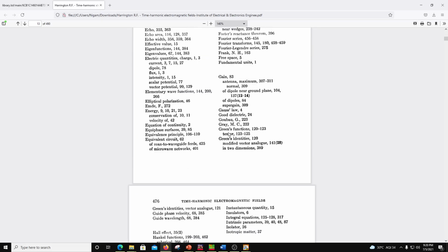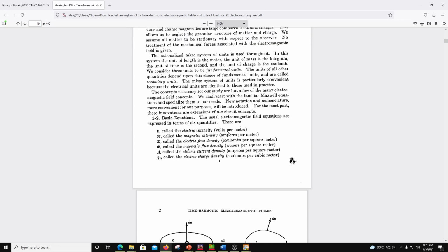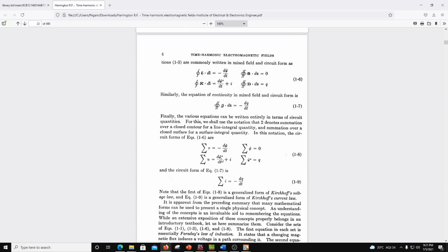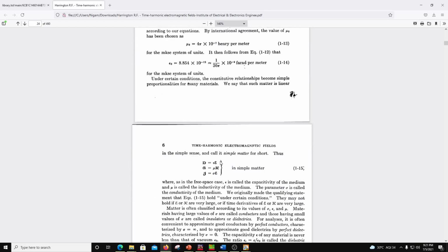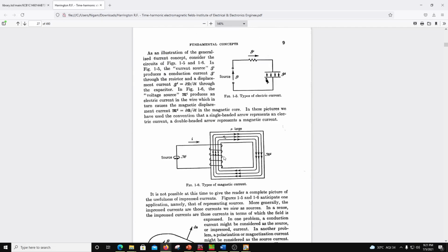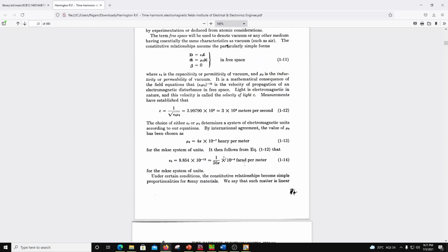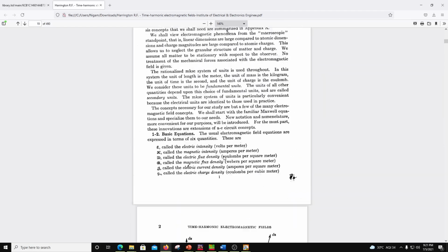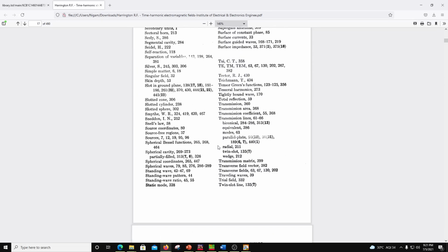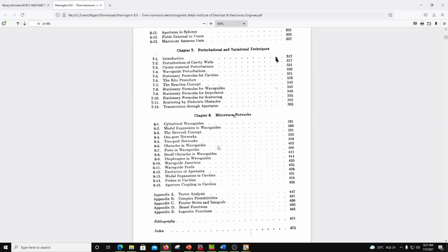In this book they cover the actual algorithm for method of moments, and the entire theory of solving Maxwell's equations, and then from there computing the voltages and currents in sheets of metal. So R.F. Harrington is the person to start with if you want to learn writing method of moments, and this will give you a lot of insight into what the simulator is actually doing.